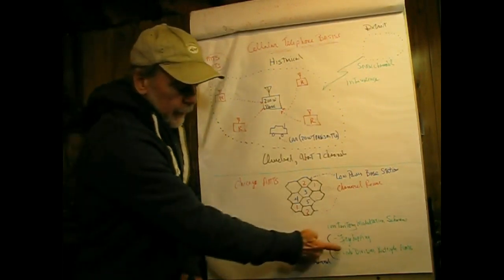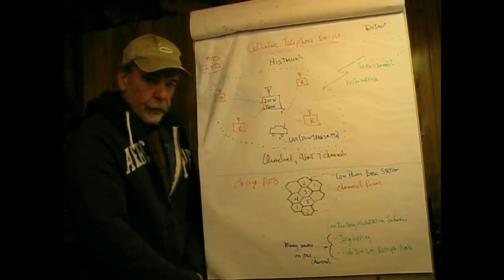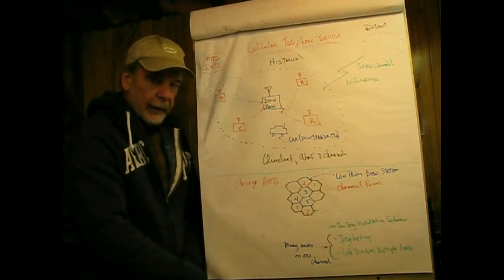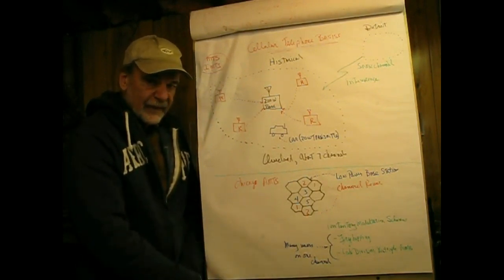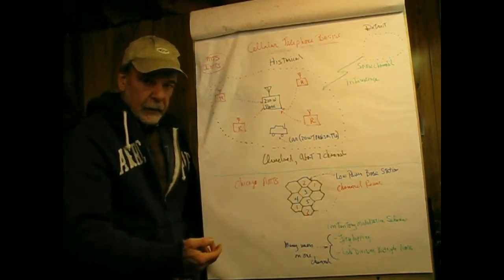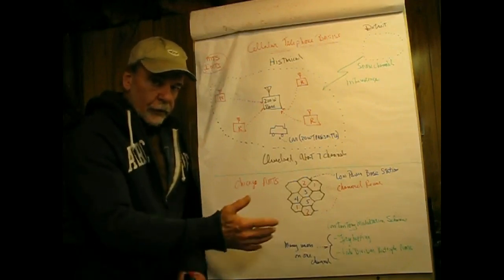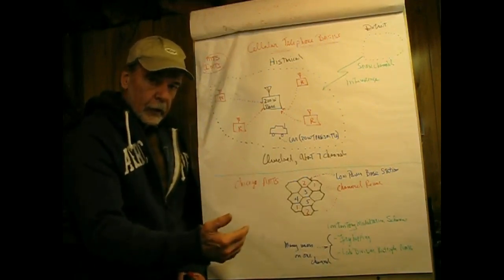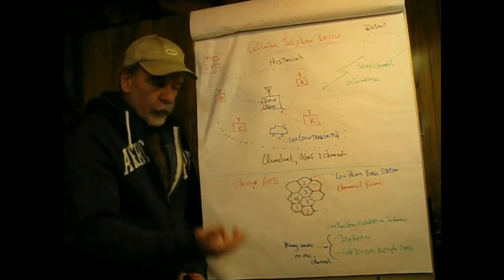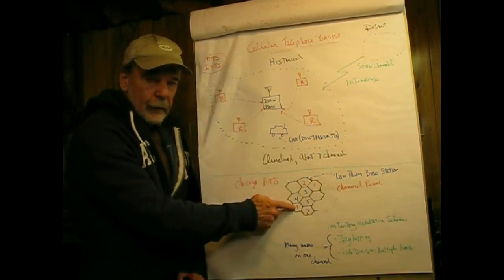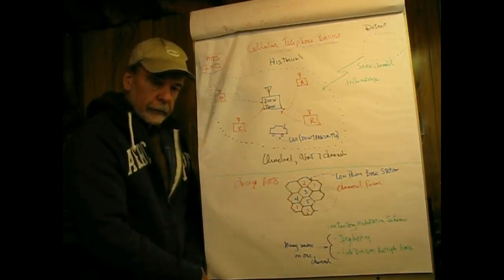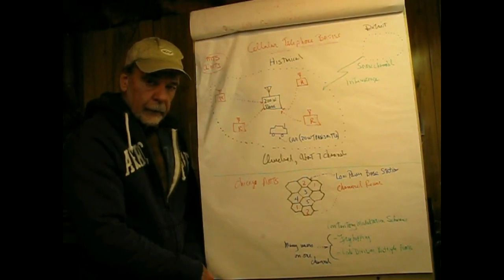Now for CDMA, it's 1.22 megahertz bandwidth, and 63 to 64 people can talk on it, and a channel or two is used for the pilot channel. That is, when you turn on your cell phone, it goes to that pilot channel and says, I am here, and then that registers, so if you receive an incoming call, it will go to the pilot channel, contact your cell phone, negotiate with it, and tell it what frequency to switch to in the cell. When it does that, your connection has been completed and you can talk.